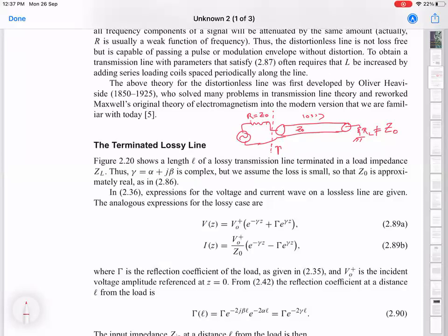What will it be? Reflection coefficient. Go down. Okay. Right. So, all of them are right. In the limit of very large attenuation, as Panya was saying, the signal is never going to come back. And because the source impedance is matched with the characteristic impedance of the transmission line, the wave will get launched. There is no reflection at that point in the first instance. But then by the time the wave propagates down the line, it's going to go down to very small amplitude.